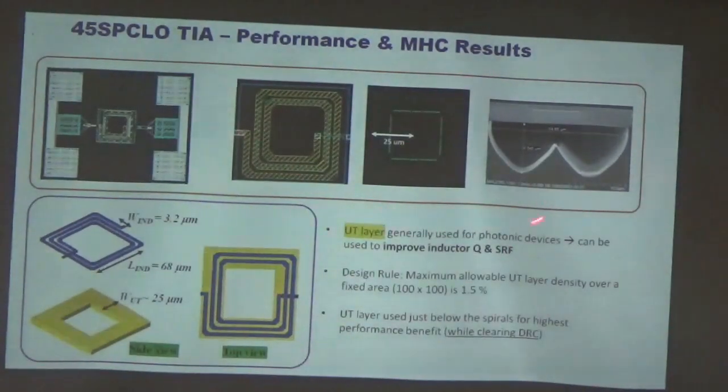There are also some innovations we did on the inductor side. These are coil inductors, how we fabricate them in IC design, like a spiral. It is done on the top metal of your IC design.